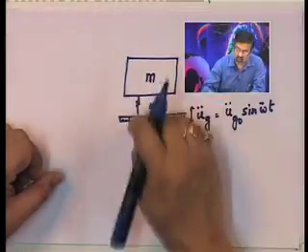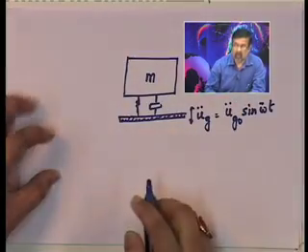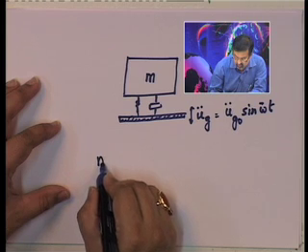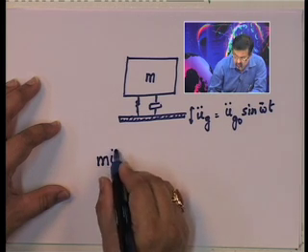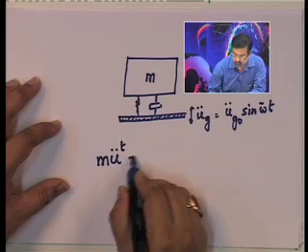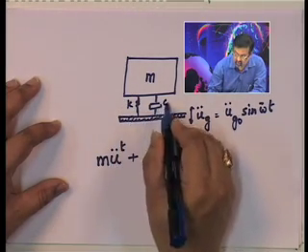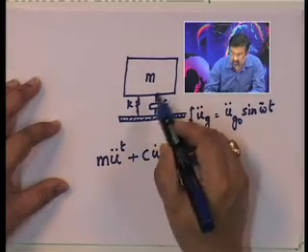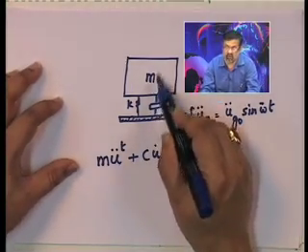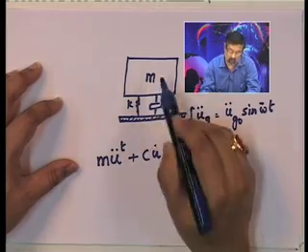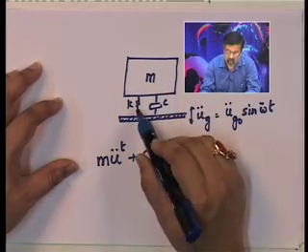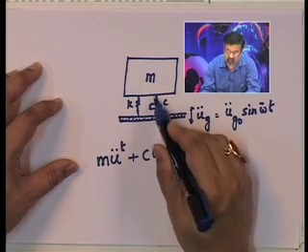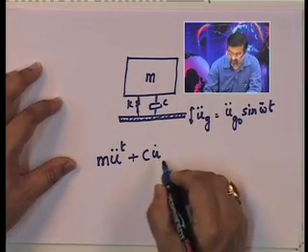So, if you look at this, now this is going to be subjected to an acceleration, and this acceleration is given by m u double dot plus this is k, this is c. So, c u dot, which is the mass into the acceleration of this mass, into the c of the relative velocity between the mass and the base.